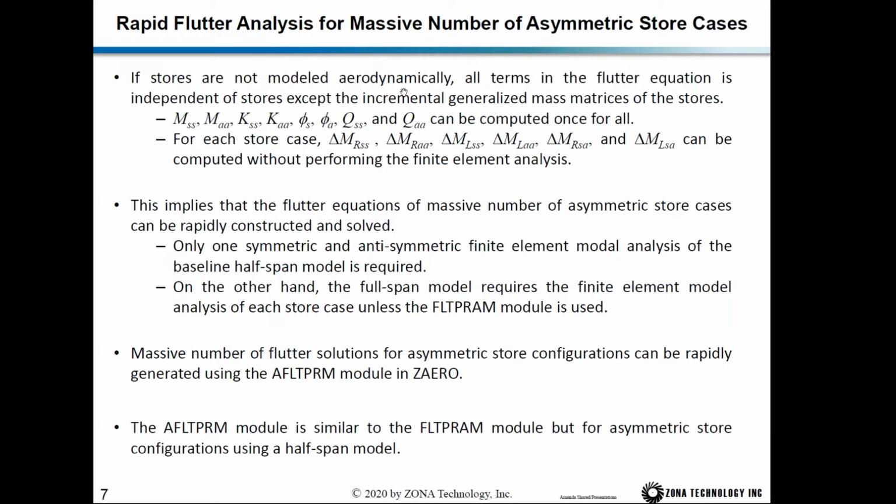And also, this asymmetric store case can be used for a massive number of asymmetric store flutter analyses. If stores are not modeled aerodynamically, all terms in the flutter equation are independent of the stores, except the incremental generalized mass and mass matrices of the store.